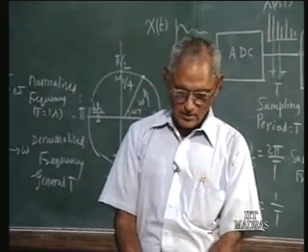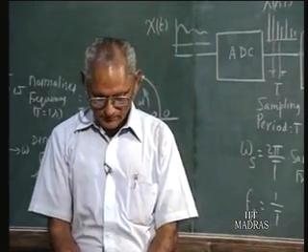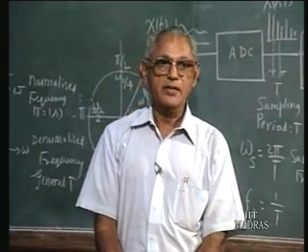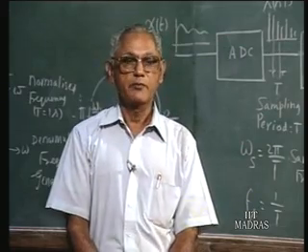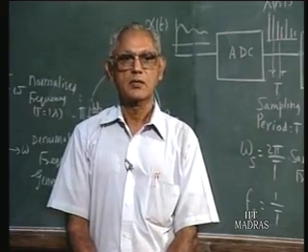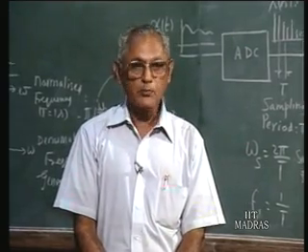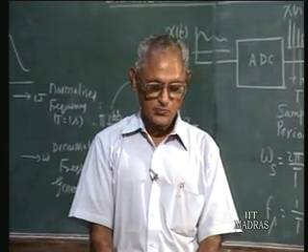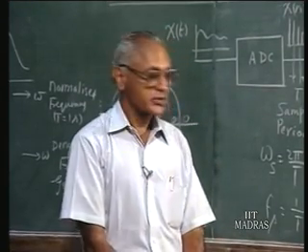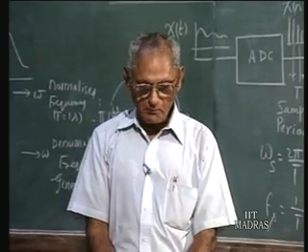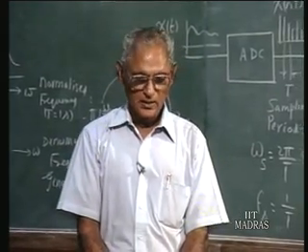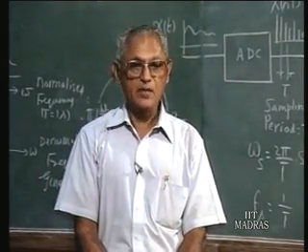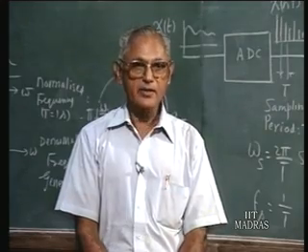We also saw that H evaluated at a point on the unit circle will specify the frequency response. There is a correspondence between the point on the unit circle and the particular frequency at which you want to find out the frequency response. We saw the various issues relating to that. Importantly, we noticed that the frequency response of a discrete time system is periodic in character.